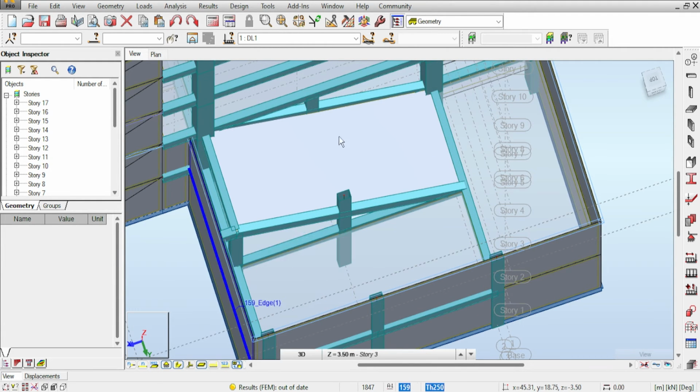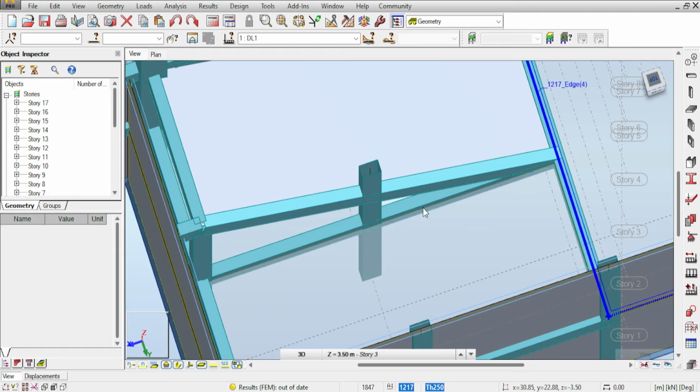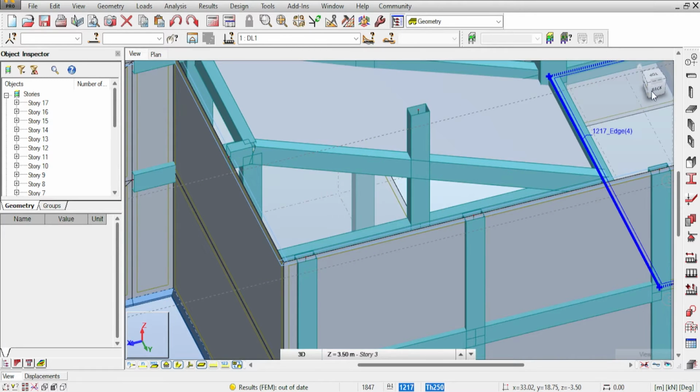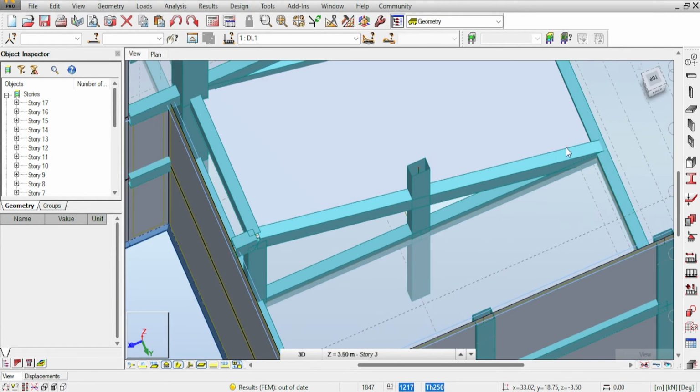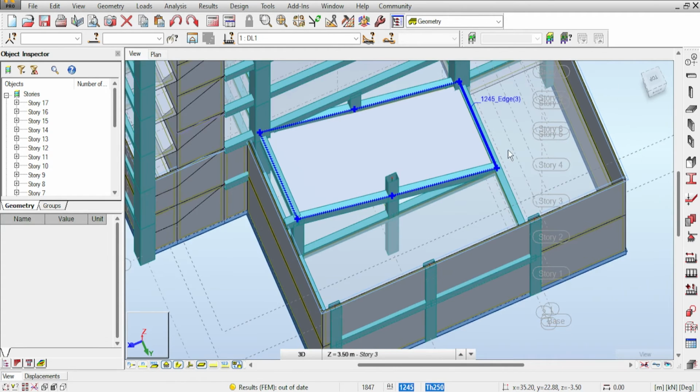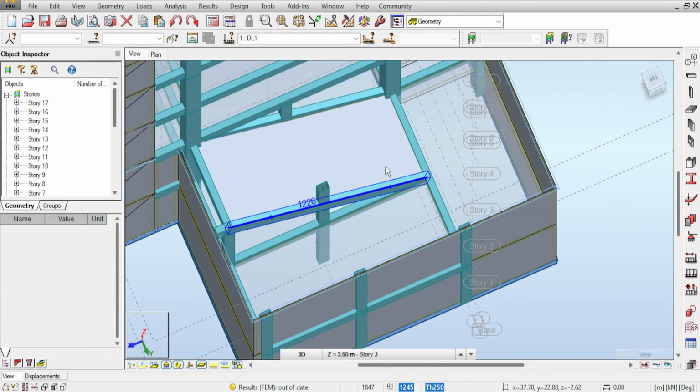Because you see, if you go clockwise, the car must go below the ramp, which will cause problems in the headspace, and also will cause problems with the ramp in the second floor, because you have to take part of the horizontal distance as your bridge inside the building. If I make it counterclockwise, it would be a little bit easier, because the car would enter here, go down half, and then turn right into the building or turn left into another ramp.